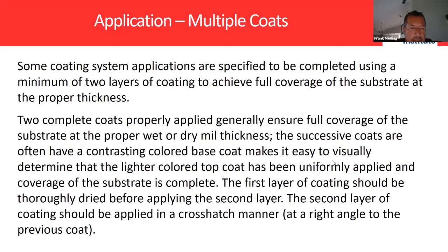Yes, well, what we were applying was the TerraPro 123 system. Well, I'm sorry, I got the wrong job in my head. We were doing the Tremco BioGuard, and the primer was installed on this concrete deck, which was scarified to a 4 to a 6, and we went ahead with the primer.